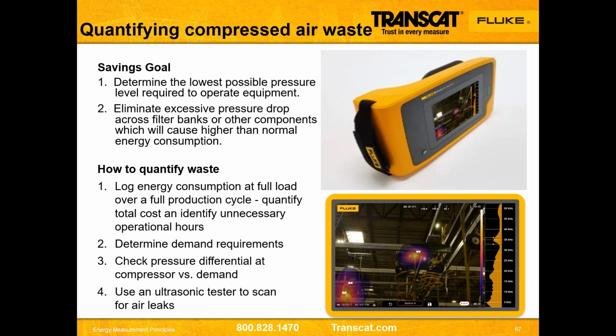So we launched a device a couple of years ago called an II900. There's now a model called an II910. These two devices are basically used for one purpose in life, and that is to find where those leaks are. So that could be compressed air, that could be steam, that could be argon, that could be nitrogen, that could be hydrogen, that could be helium, that could be any number of types of gases. And this is looking at pressure changes with 64 sensors that are wrapped around a camera. We have the ability to scan very large areas for leaks and quantify where they are visually.